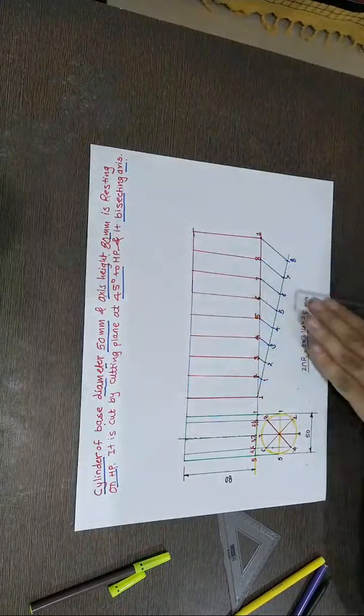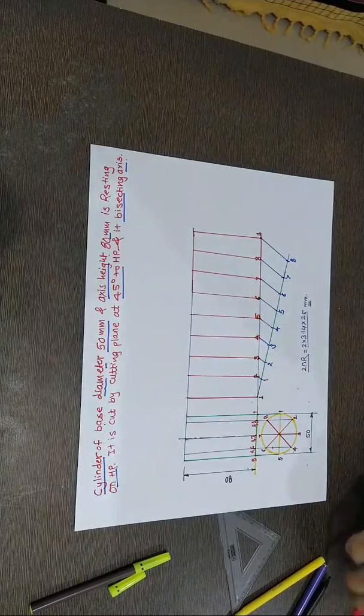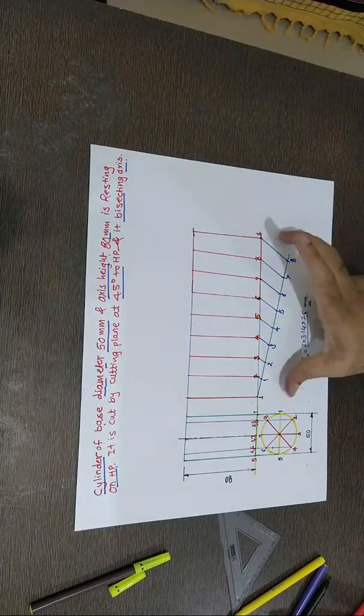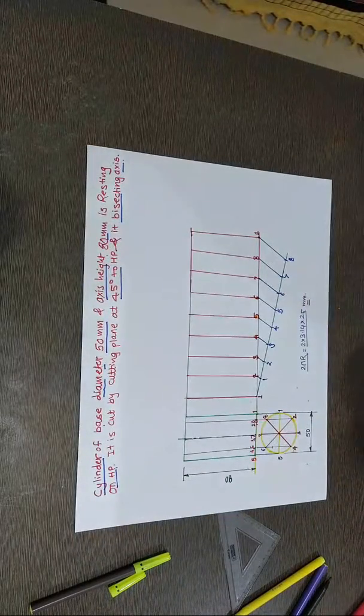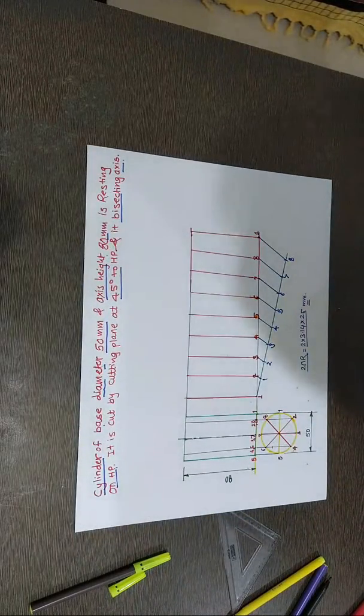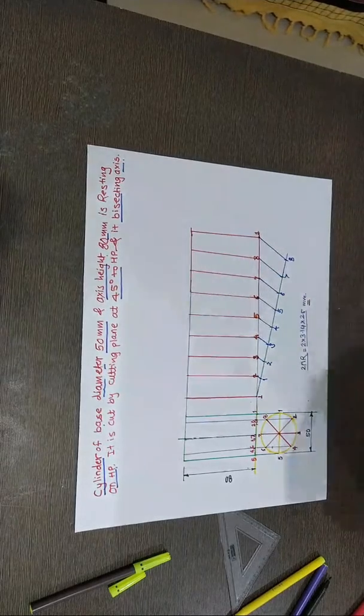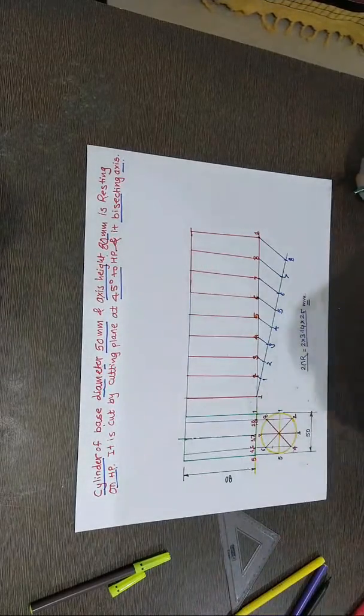Of course, they're exactly vertical. Now this is the development of the pi d distance, or circumference of the circle of the base. The height is equal to this. Now, it's logical and very simple. We had already the prism development, so you can easily draw this.